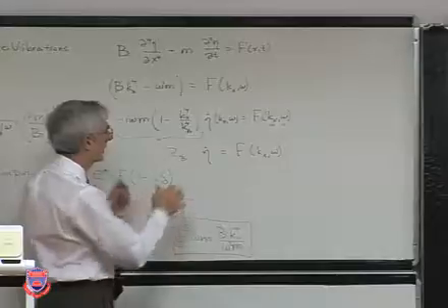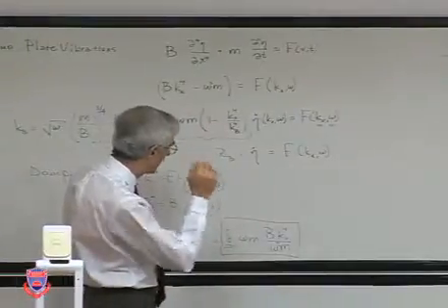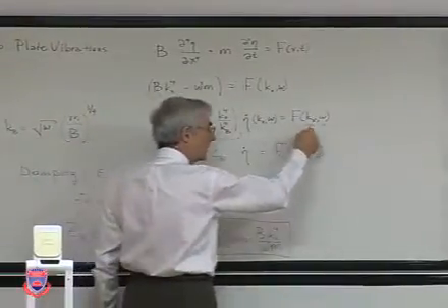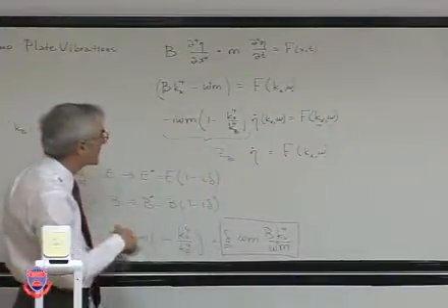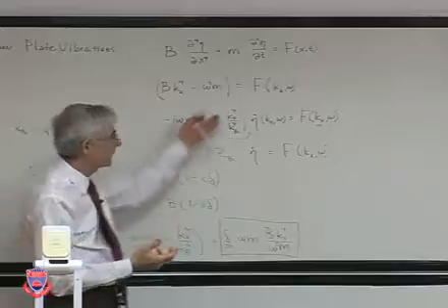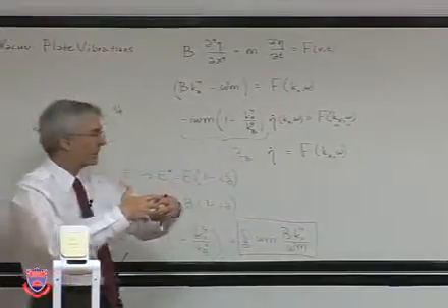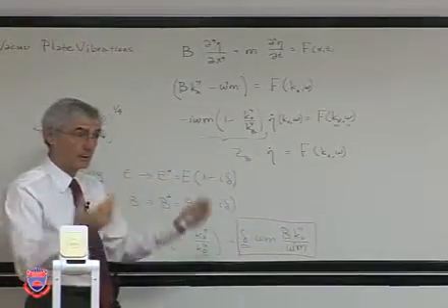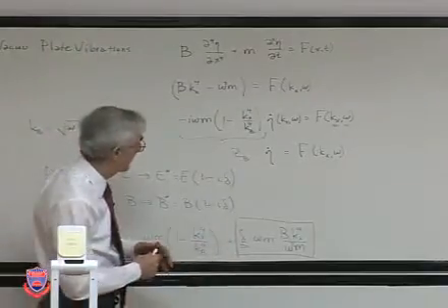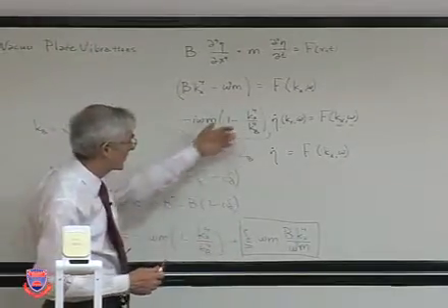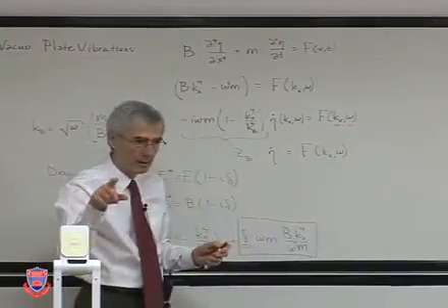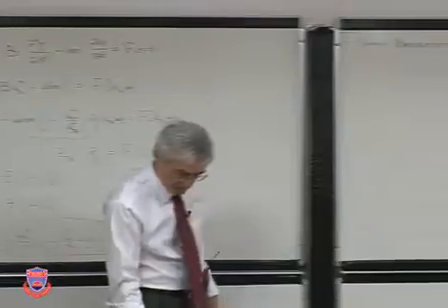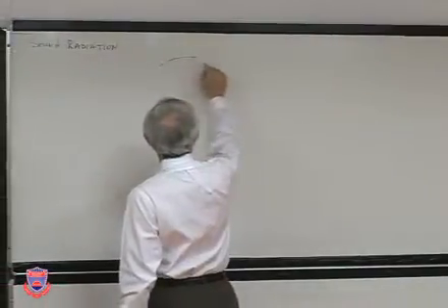So when we look at this, we say, okay, for a given wavelength or wave number for a given frequency, you do solve it for each and then synthesize them through inverse Fourier transform to get the spatial response of, in this case, the plate. So what we do is let's just take one bending wave and take a look at what the behavior is, which is what we did before.